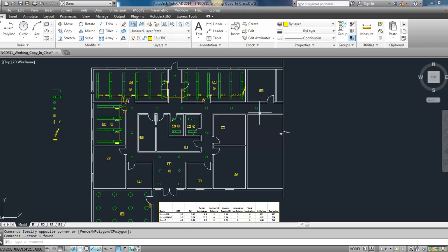And essentially, if we want to cheat it a little bit more, we'll delete that one there. Remember, this is a break line. It means that there's more building this way, and whoever's doing that part of that building, they'll have to worry about that one luminaire, maybe put it on a separate circuit starting at that point for the rest of the building. And it might even be on a different panel as well.